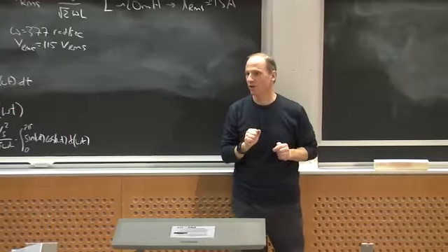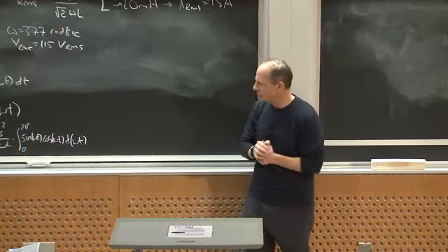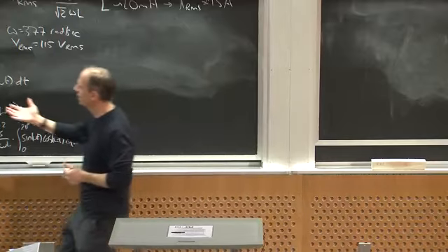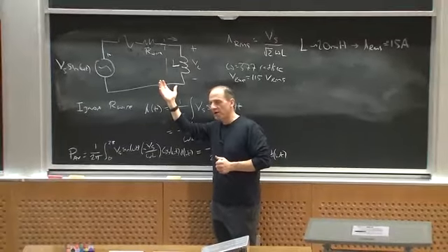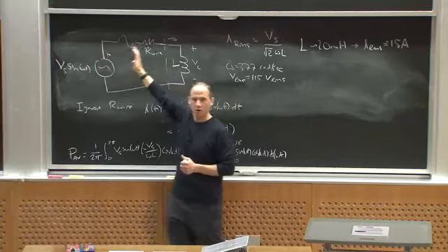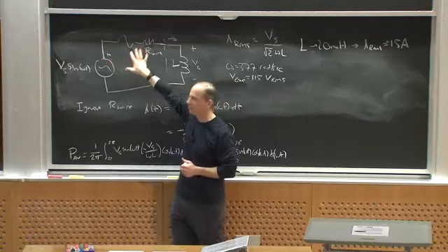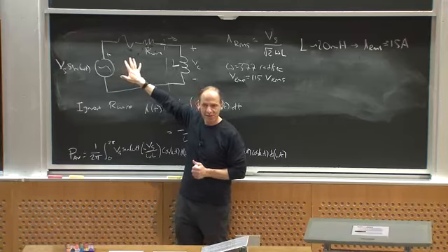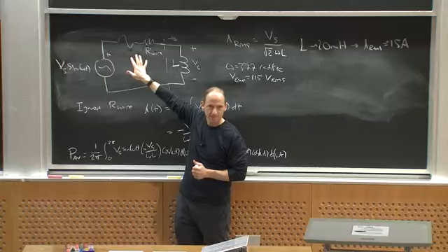I draw any more current, the breaker goes, okay? So plugging in the inductor hasn't used any average energy, but it has degraded my ability to draw power from the source, right? I've utilized the capability of the source to deliver me energy even though I haven't used the energy, okay? Any questions about that?